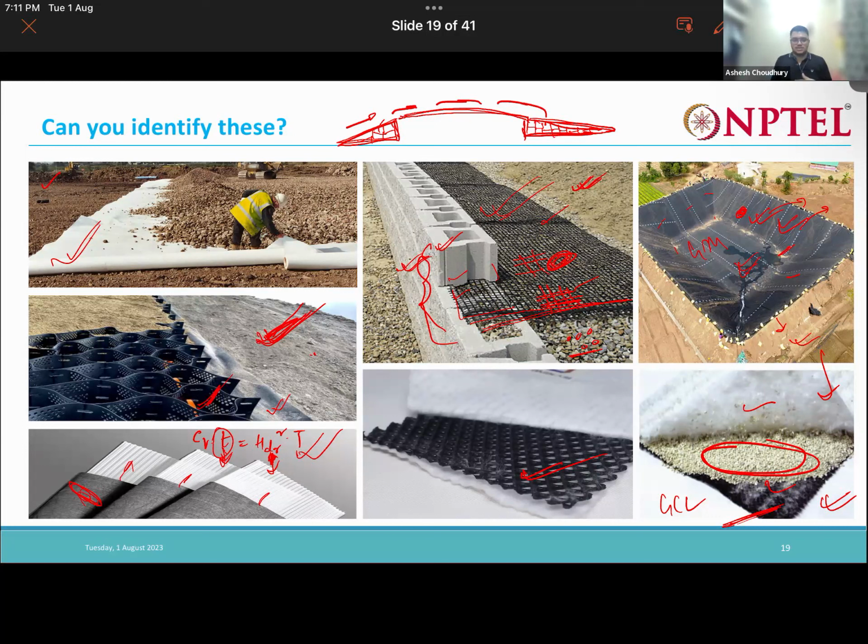The foundation soil, above which the reinforced earth structure of the approach was to be constructed, was a little soft soil. So PVDs were installed to accelerate the consolidation process, so that after the consolidation occurs in say 2 to 3 months, the reinforced earth structure can be built over that.